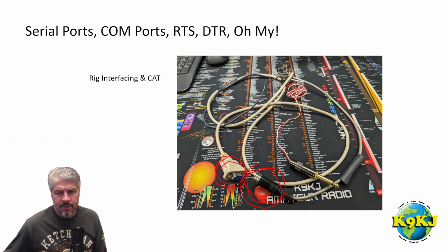And this would connect into my Kenwood, and I would have to make sure that pin 5 was ground, and then pins 2 and 3, which are the RX and TX pins, would be appropriately assigned to this DIN side here. Now you also see that there is a 1/4 inch phono plug here, which is something that you could use to key the radio.